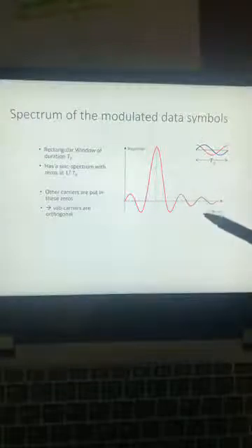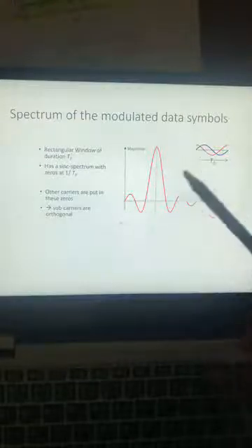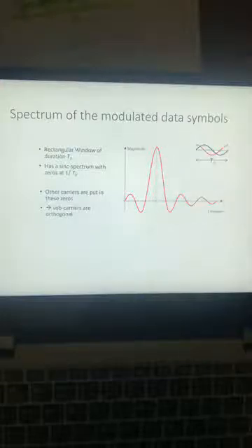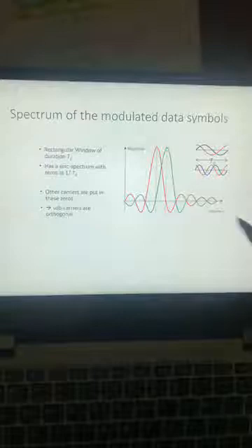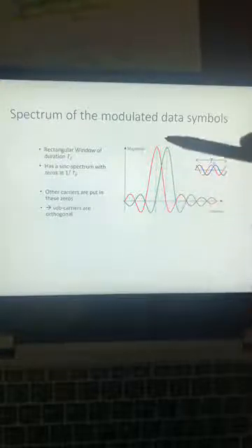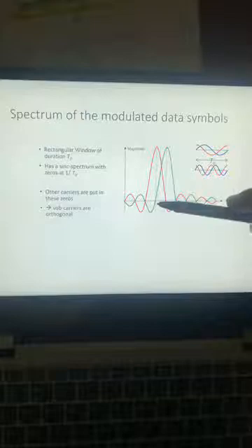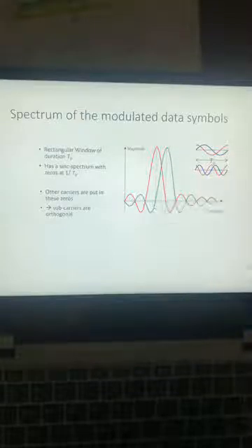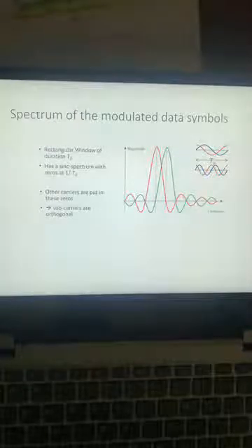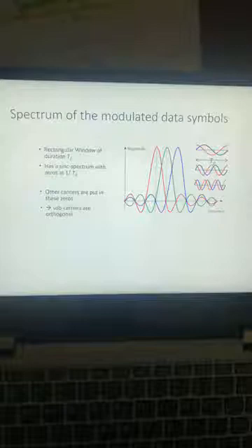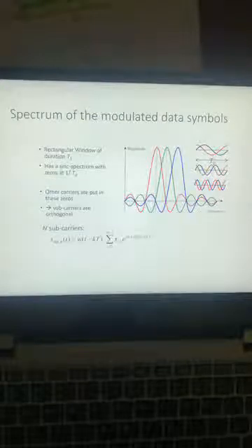If you plot the real part of the exponential, this is how its Fourier transform will look. This is the frequency of the carrier, and this is called OFDM because every carrier is orthogonal to the other: at the peak of one carrier, a zero of the other carriers passes through. And if you plot n of these carriers in frequency, this is how they are going to look.